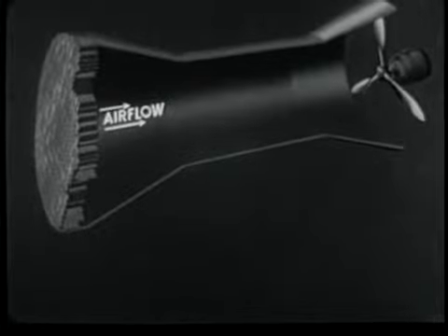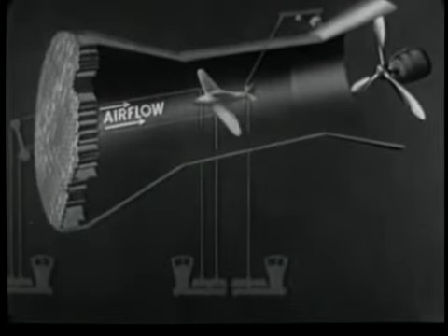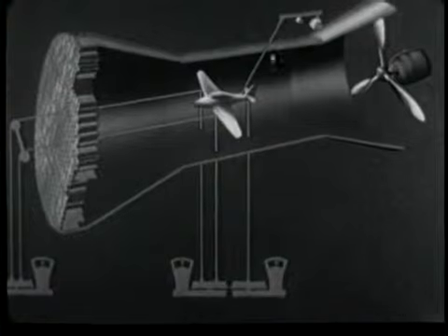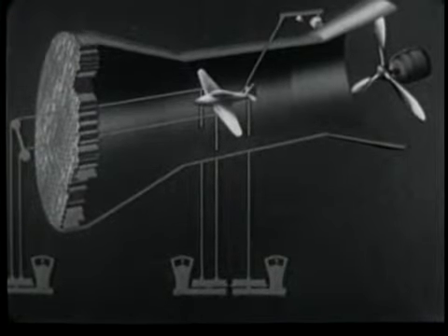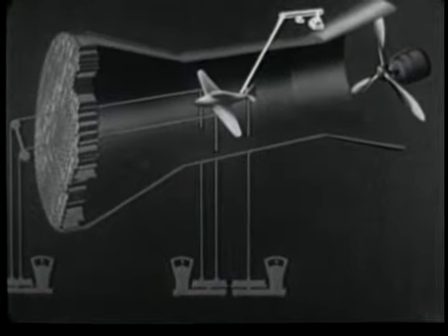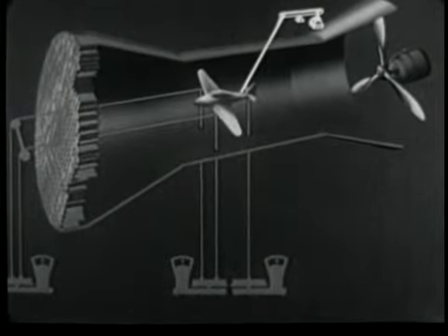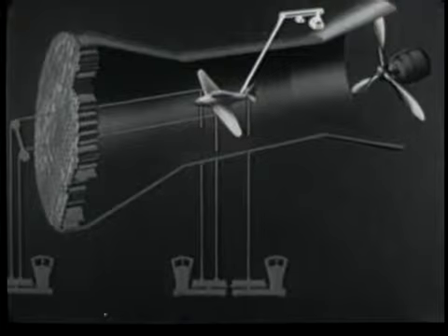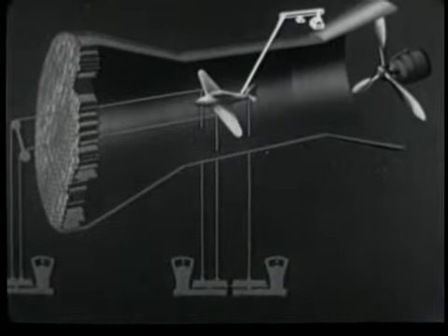When lift and drag of an airfoil are to be measured, the model is placed in the chamber and supported by wires. One wire runs from the model through the top of the tunnel to a balance arm which is weighted so as to maintain tension and compensate for other forces.